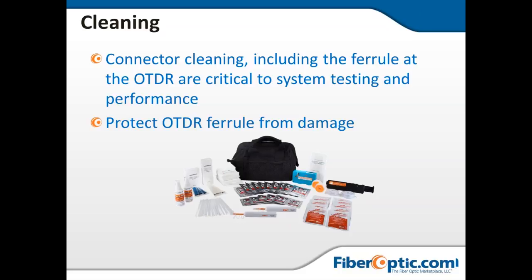Rather than just mushing it around in there and getting it to spread around on the fiber end face, it'll actually get in there and clean it and remove it by spinning, and it's kind of like a dental floss, but it spins over the end of the tip of the cleaning device, and also rotates around like 360 degrees. So it's spinning and advancing all at the same time, which basically causes a wiping action away and removes that dirt and debris from the ferrule. So make sure you're doing that regardless of what OTDR you go with at the end of your decision.